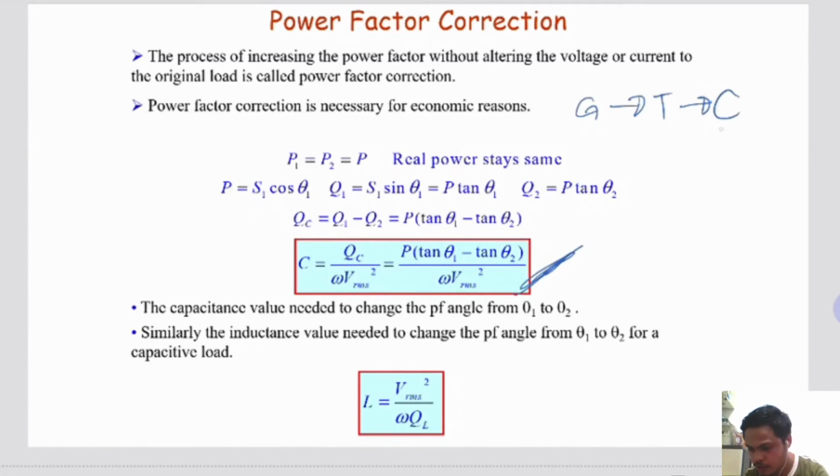Okay, so this transmission sector or the NGCP buys power from the energy producer company, and this electric cooperative also buys power from transmission or from NGCP, the real power and the reactive power. So if you can reduce this reactive part, you have to pay only the real power in the system.